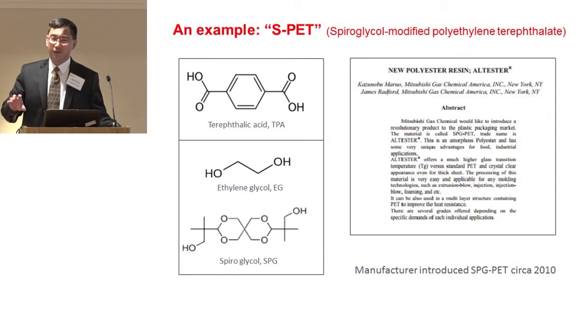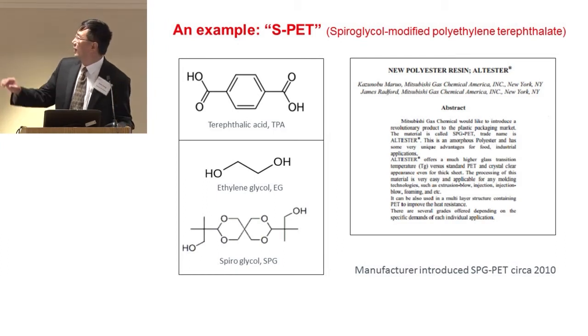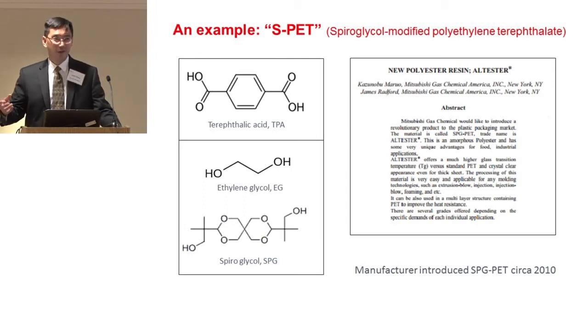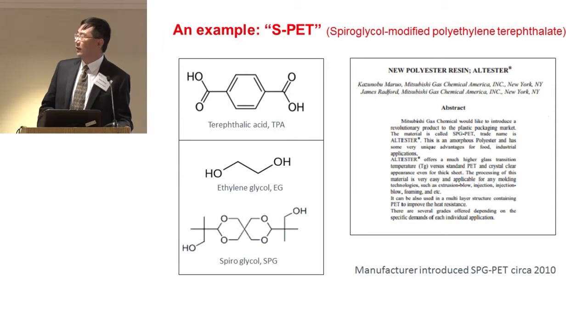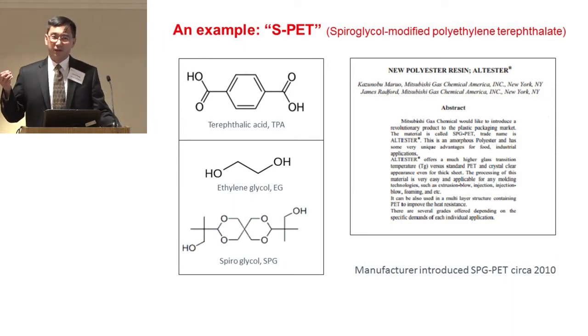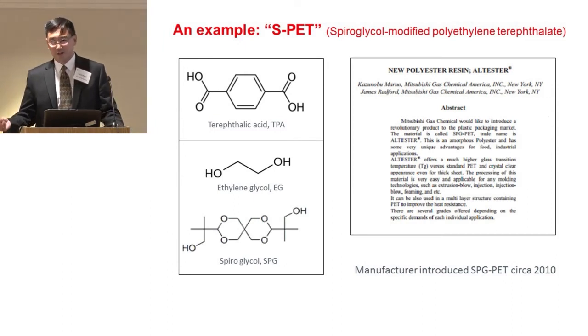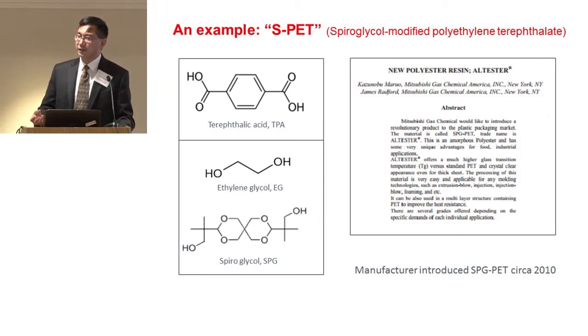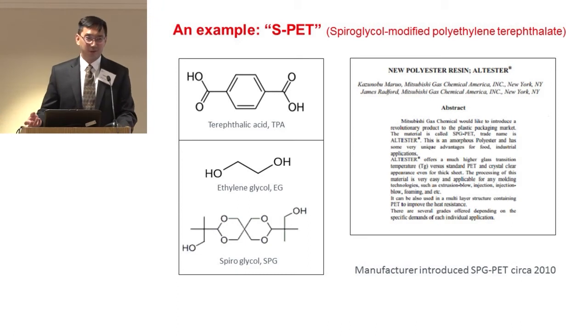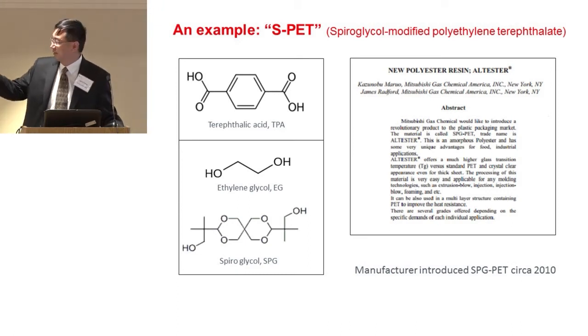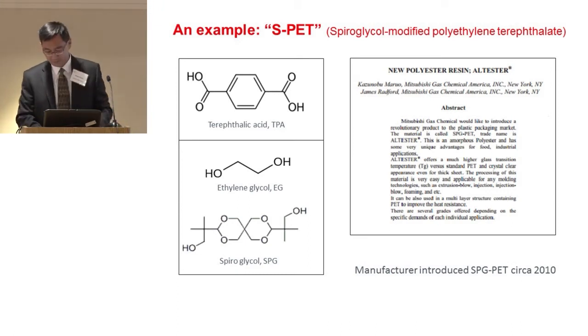There's ethylene glycol and diethylene glycol, but for the purpose, just say terephthalic acid and ethylene glycol is what we use to get the polyester bottles. If you can modify that to give it more heat resistance, to bring the glass transition temperature above water boiling temperature, so that you can put it in a dishwasher, okay, you probably want to use it.